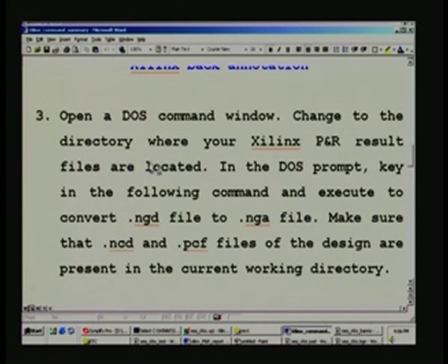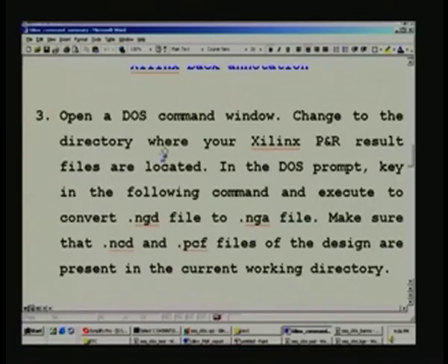In fact, while RTL coding, I mentioned the technological dependence, you may give some gates, even assuming the synthesis tool keeps it intact. Even then you have to go through all that and find out whether the total delay is really up to the mark. There may be some critical paths which you may take lightly now, and later on that may blow out into a big problem. So it's always better to do it. After all, you are going to do it only once in a lifetime for the product. So why don't you do it completely? And hardly, it's going to be a couple of days, not more.